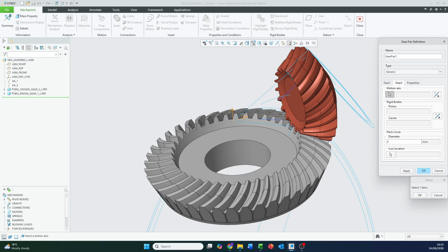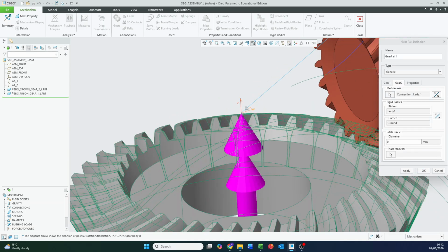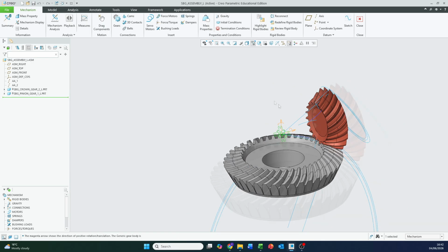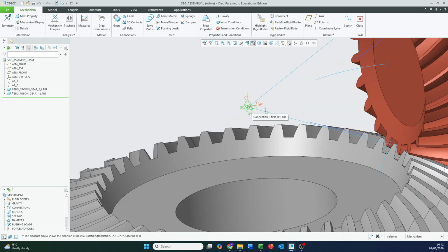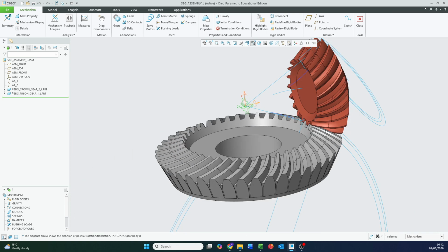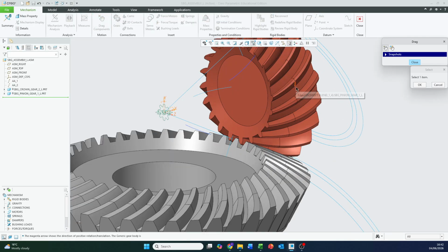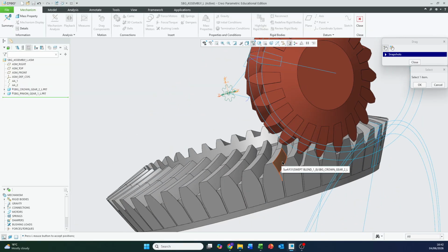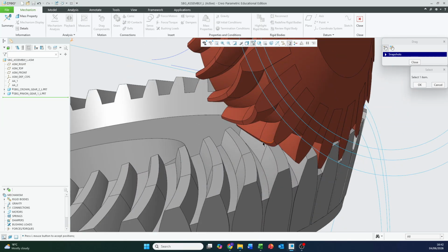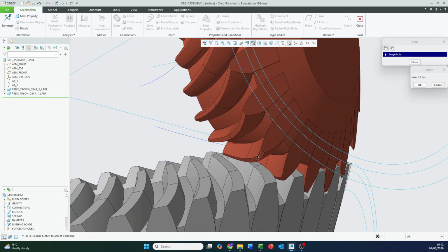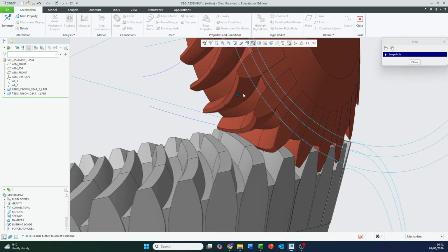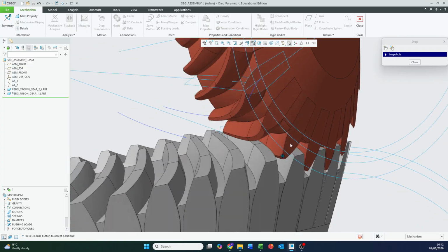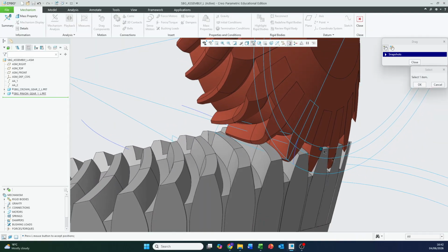And for gear 2, you have to select their respective pin icons here. It will be 40 teeth, apply, and press OK. The gear mechanism has worked, and you can tell that because you have these gear icons at these connection points here. And now if I drag components, you can see how the gear bevel, forgive me, I'm fumbling over my words there. You can see how these teeth mesh accurately and oh so satisfyingly.